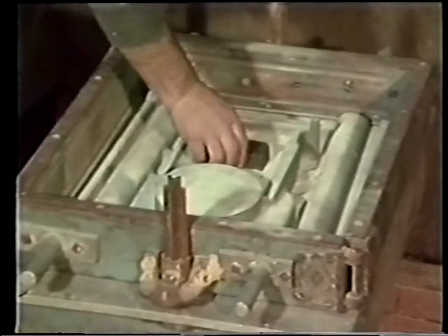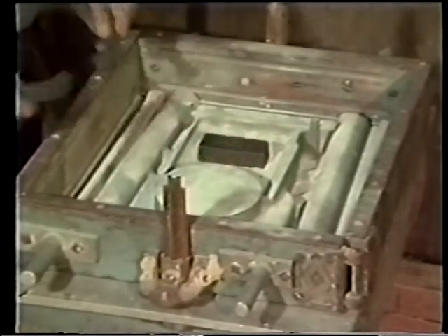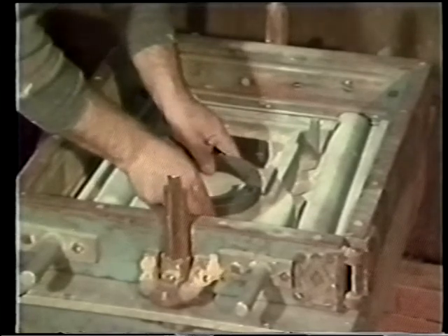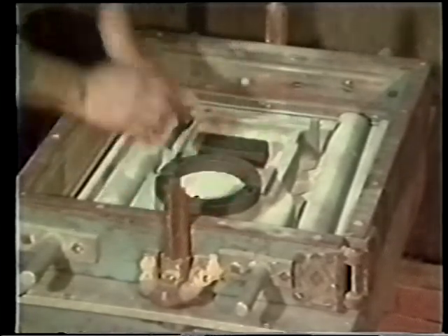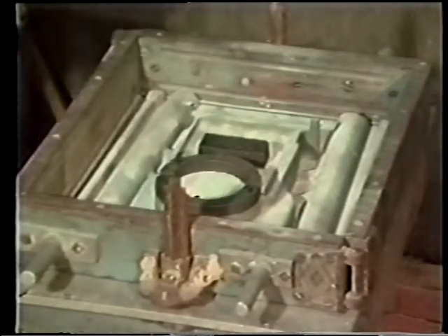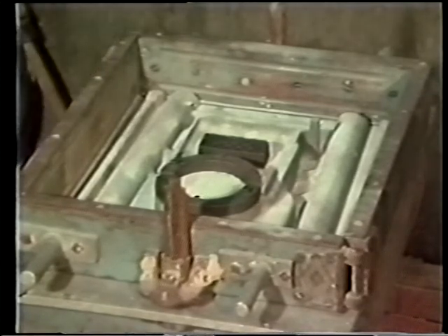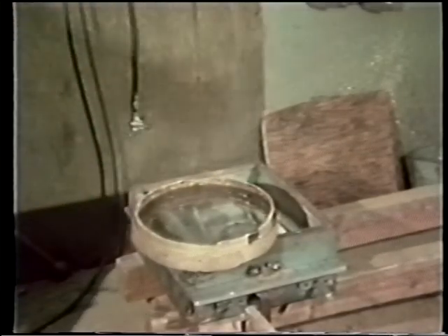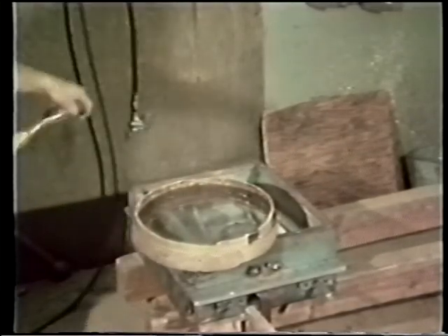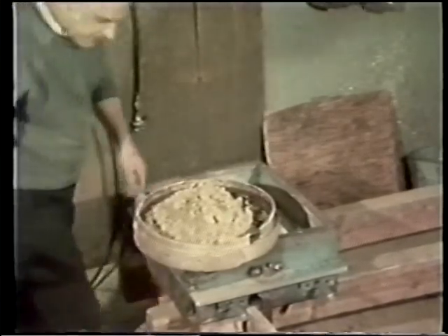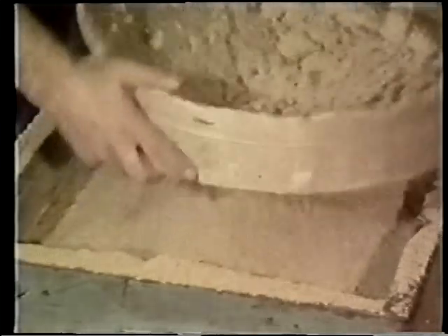Pieces of iron called chills placed within the mold cause faster solidification of the molten metal in certain sections. This creates superior properties in these high-stress areas. Next, sand is placed around the pattern. This sand is specially formulated so that it will quickly harden after production of the mold is finished. This allows for maximum efficiency in production of cast parts.